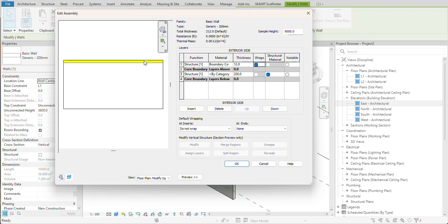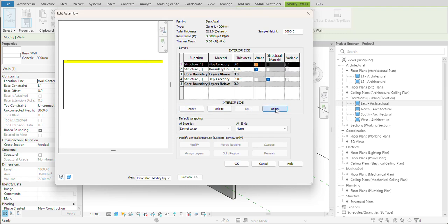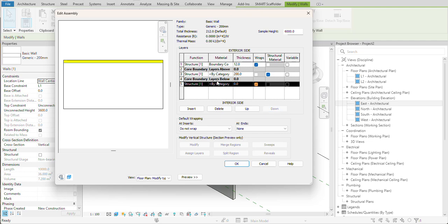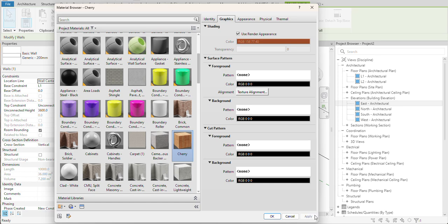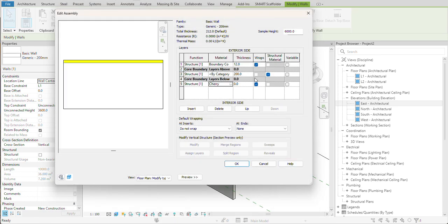For the plastering inside, now you can take one more, go down. Here again you can choose a different color. Suppose you want this wooden one, render appearance, and okay. Again you give 12 mm or 20 mm, whatever. If you are using tiling, you will take it according to your need. That's the plaster, inside and outside, both the outdoor and indoor faces. Now I'm doing it.